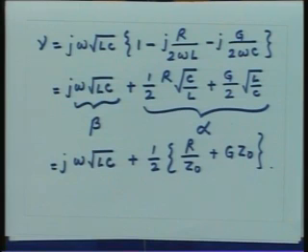One would however notice that the condition which we have defined for the low loss is now in terms of the primary constants of the line. In the data sheet, however, for a transmission line, the primary constants are rarely mentioned. The parameters which are mentioned for a transmission line are the effective phase constant on the line or the velocity on the cable, and the attenuation constant of the line either in terms of dBs or in terms of Nepers.